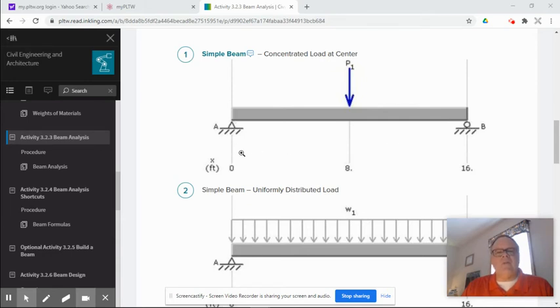You know both of these have a vertical reaction to the downward load of the point load here in order to maintain equilibrium. There has to be a normal force going back up, or a reaction. So for both the concentrated load and for a distributed load, we first of all have to calculate the reaction at A and the reaction at B in order to then create what we call shear and moment diagrams